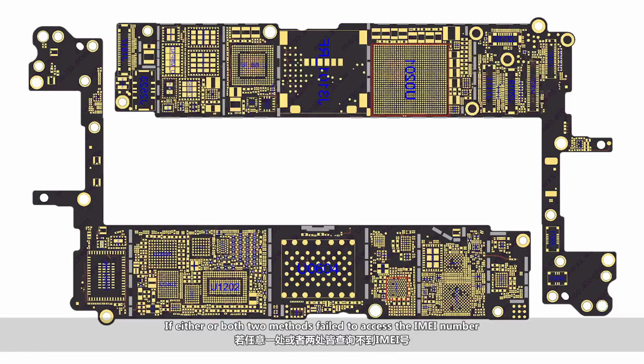If either or both two methods failed to access the IMEI number, then the fault is related to baseband CPU or relevant components on the RFFE bus, and we need to check components on the RFFE bus first.